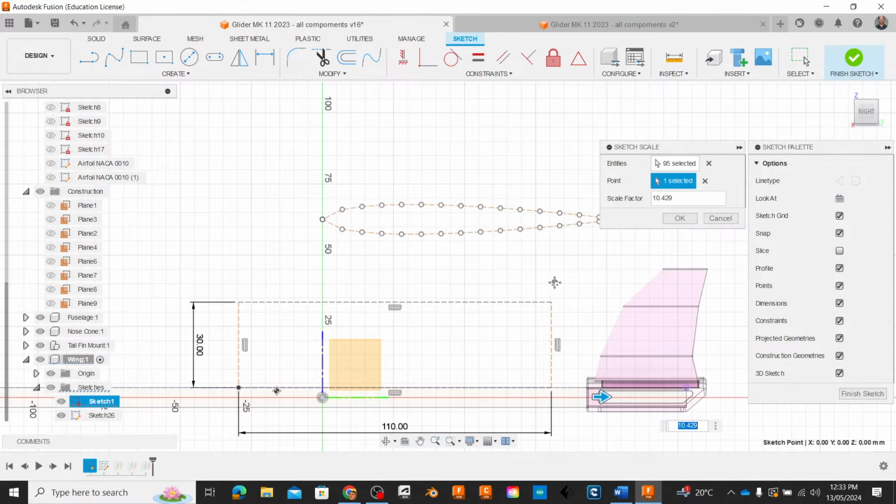So I will select the sketch, go modify, move copy, and I'm just going to click once on the rotate button. So here, -5 degrees, I'm going to go to -4 and see how that looks. -3. That's pretty good. Next, what I'm going to do is draw a flat portion.